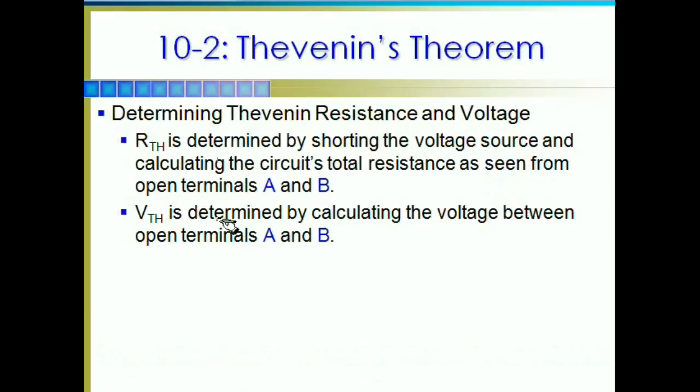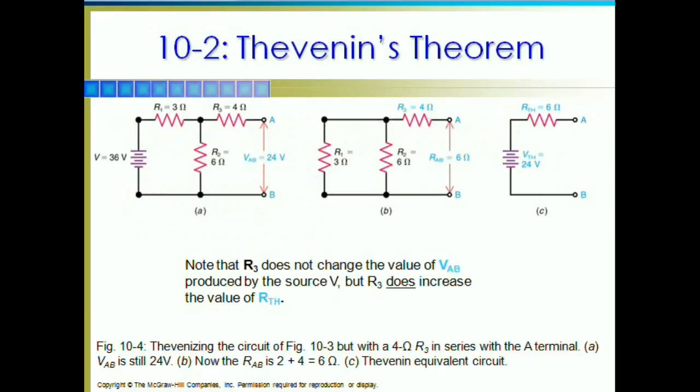Alright, and here we have the same instructions I just gave you. In a case of multiple resistors here, I've got a different type of series parallel circuit, but this is still my load out here. Well, I'm going to pull that load out once again and look back from points A and B.